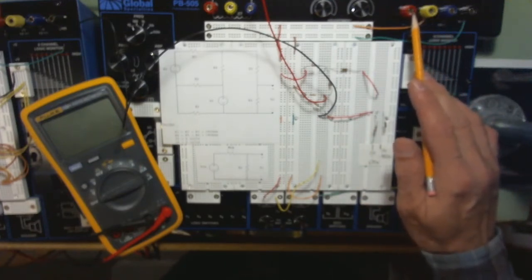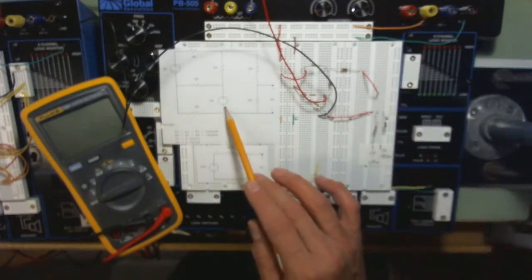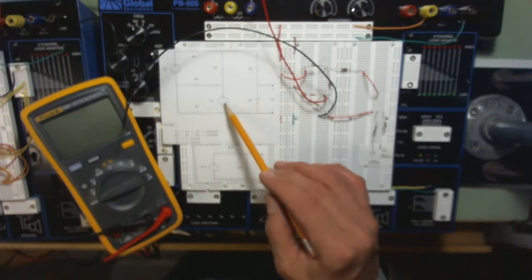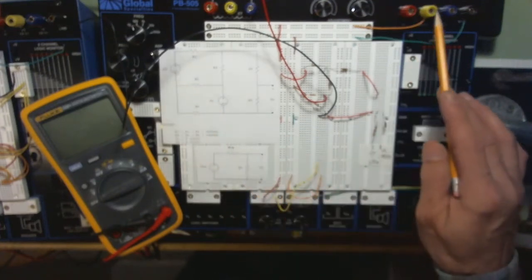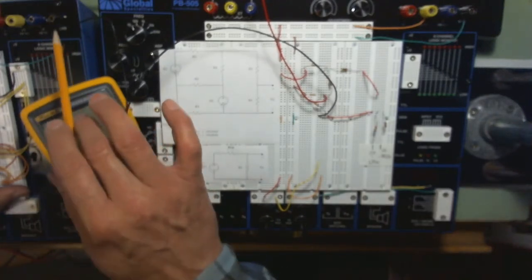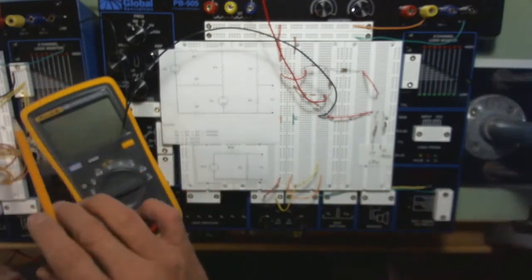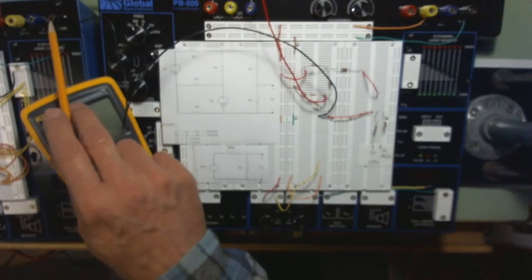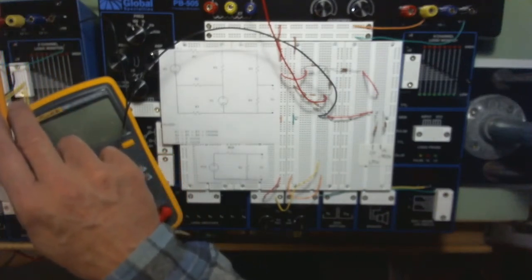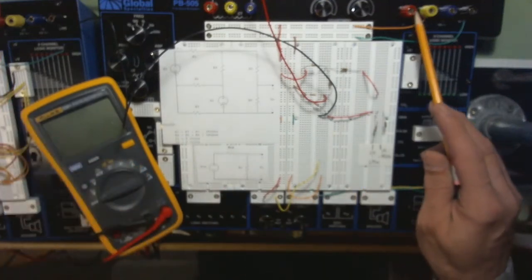And there was the 5 volts, and on face value, you might think you could use that 5 volts. But again, this terminal here is not at the same potential, and these are at the same potential inside this board, so they're not independent. They have the same ground state. So what I've done is I've got a second one over here, and it's kind of off the screen, but basically it's exactly the same as this one. I'm using the ground lug here, and the 5 volt lug like that.